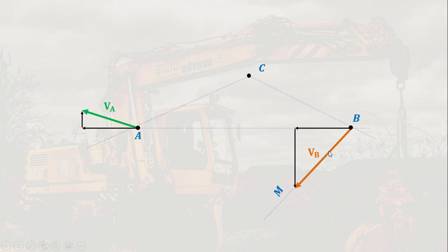So now that we know the absolute velocity of B, we would like to get also the absolute velocity of C. So it's important that we solve first the point where we know the direction of its motion. So do not solve yet the point whose direction we do not know yet. Always focus on the points that we know the direction, because as you can see here, for A we know its absolute velocity, we also know its direction. But for point B we do not know yet its absolute velocity, but we know the direction. That's why we solve it next to A.